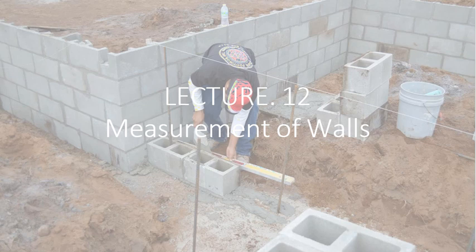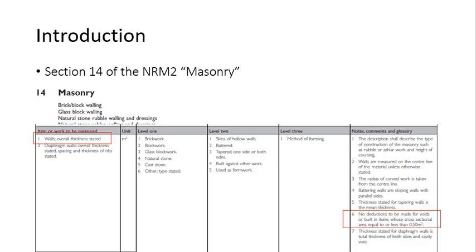Measurement of the walls. We have already done some part of it in the substructure, so you already know some of the topics and we can go through it quickly. This is the NRM section which deals with the masonry walls. There can be different types of masonry walls, and we will have a look at them. You can see the types over here as well. I will show you in more detail, but this is section 14 of the NRM2.